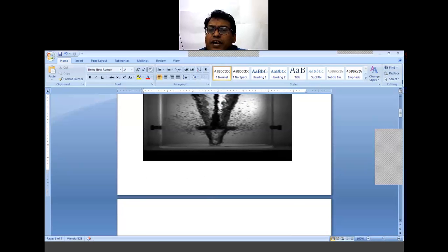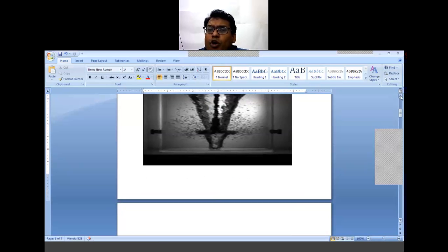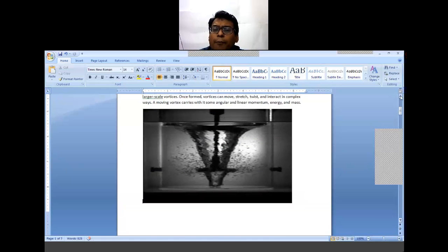Besides that, this generated vortex is also going to cause cavitation if you are using a pump, or generated bubbles. It sucks the air inside, and as it sucks the air pockets, they will hammer your impeller. This continuous hammering of these air pockets or air bubbles is going to deteriorate or destroy your impeller. Pitting of the impeller and erosion will be observed.